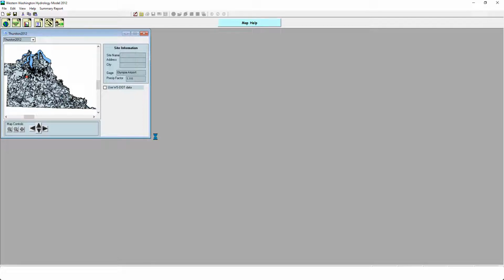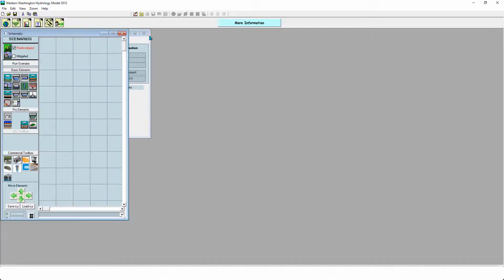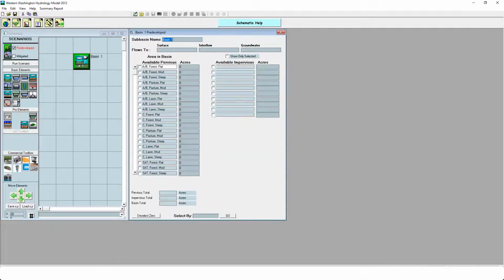This is going to give us historical rainfall data going all the way back 60, 70 years. Using this historic data, we can determine what events are likely to occur in the future based on past events and what the soil conditions and runoff is like from the site based on these historic rainfall events. What we do in this software is we import our land use basin, and we're able to create a land use from the software. So let's say we had 4 acres of C-type soil that was flat forest.